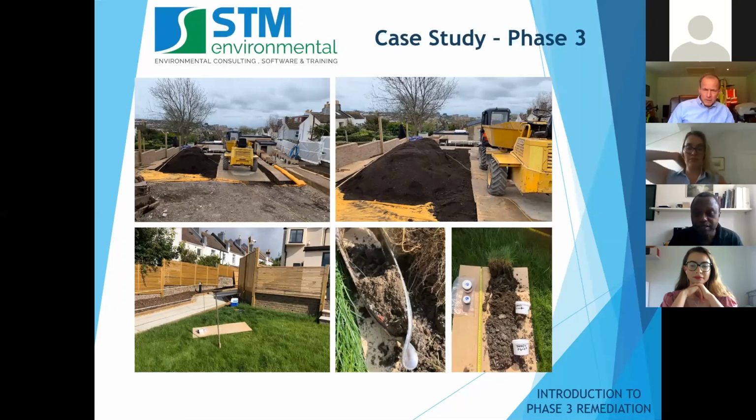I won't go into the details of it, but essentially they hadn't done it properly. So we had to have a prolonged discussion and explanation of why it was important that they should do it properly. It's amazing. They'd laid the geotextile in clean topsoil, and then later on, they had some more waste soils, which they dug up somewhere else on the site, which they then probably decided to lay on top of the clean topsoil.